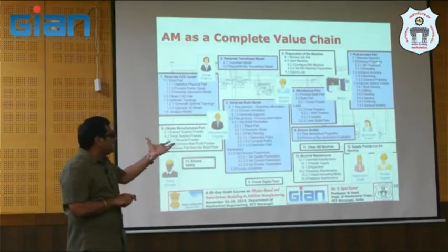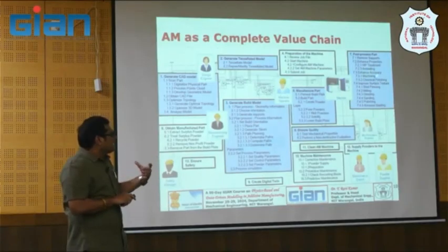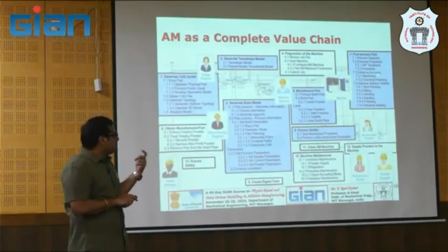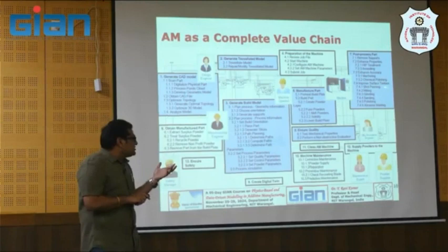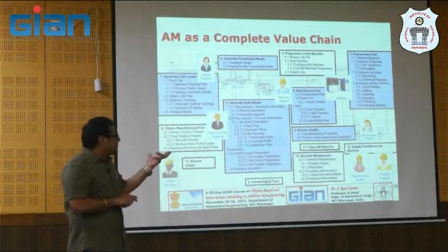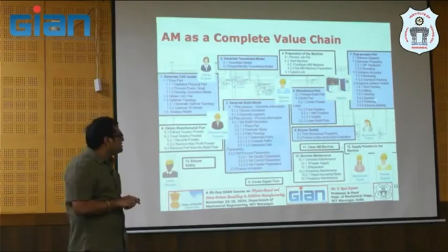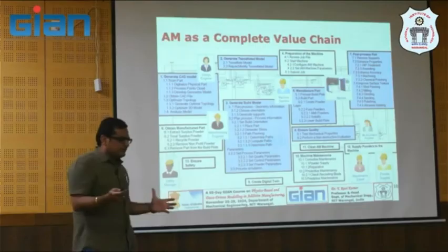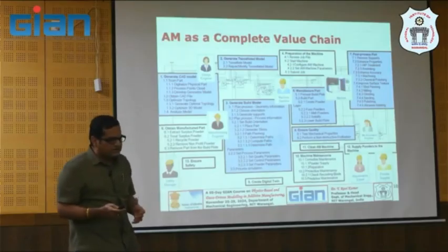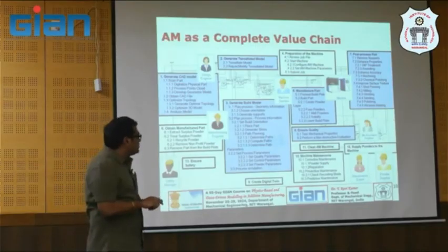It may be through hipping or annealing, or maybe you're not satisfied with the accuracy, then sometimes it may be subjected to machining, and sometimes it may be chemical polishing and surface texturing, right? So nowadays you have even shot peening, milling, grinding, sanding, polishing, abrasive blasting. You have the post-processing. Again, it depends on the application and the design requirements. So then the parts will be subjected to post-processing, right?